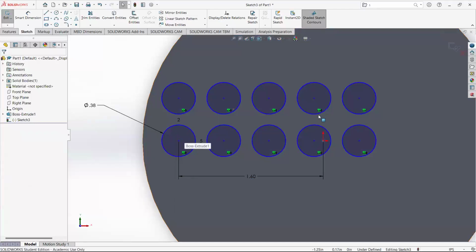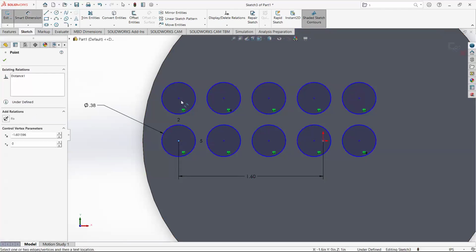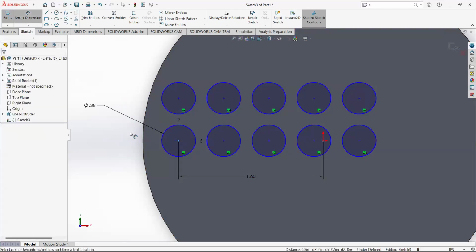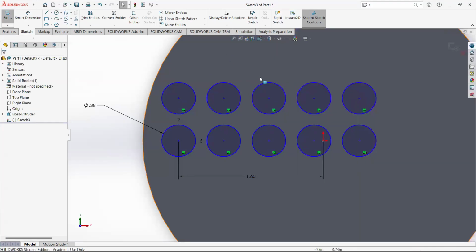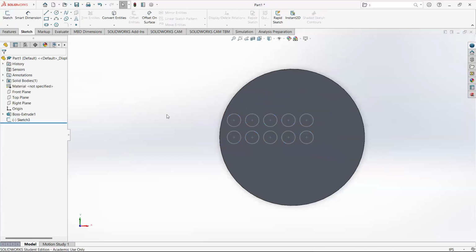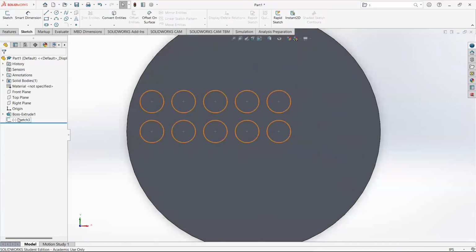And I'm going to leave it where it is. Even if I dimension this, these things stay blue. So if I smart dimension here to here, actually, I need to let those get locked down. So except, right, I've got a sketch of a two-dimensional grid now.